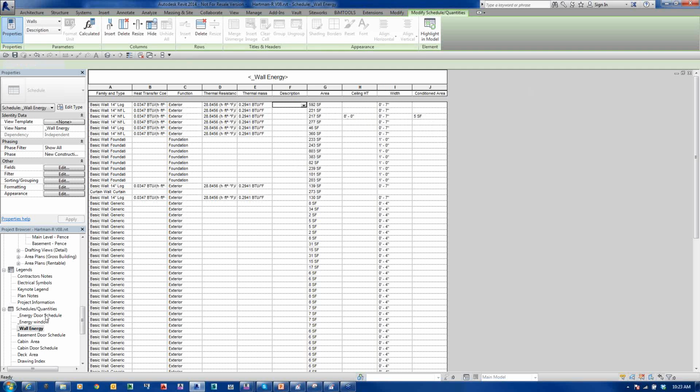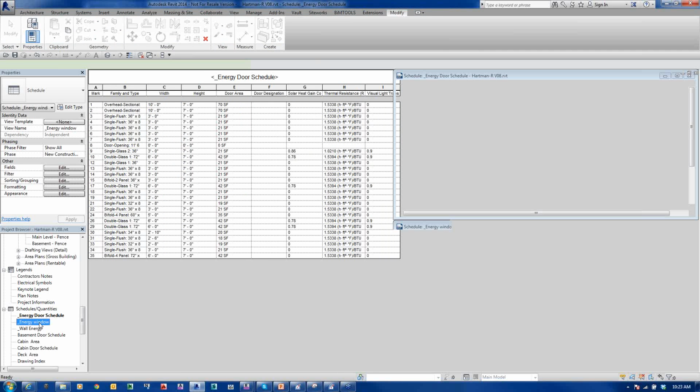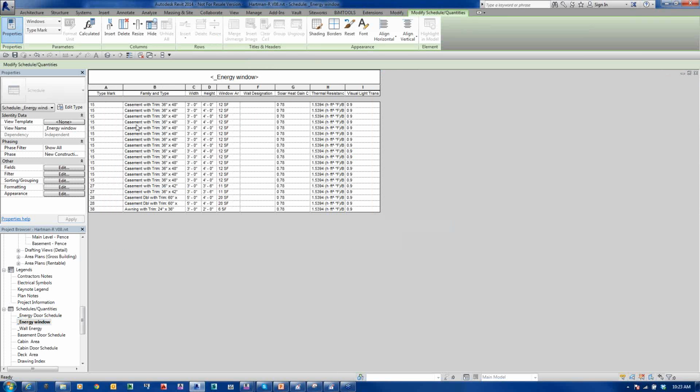The other thing we need to do is go in and set up our doors and our window schedule. So I actually go over to the window schedule in here. I've got all the different windows. I've also set up the wall designation so it corresponds with the correct wall. So when I set that wall description, I'm going to put the window description to follow the wall description in there. So if this is the north wall A, I would put that wall description in here so I'm getting the right window inside the right wall.